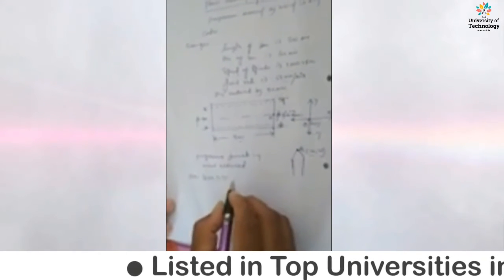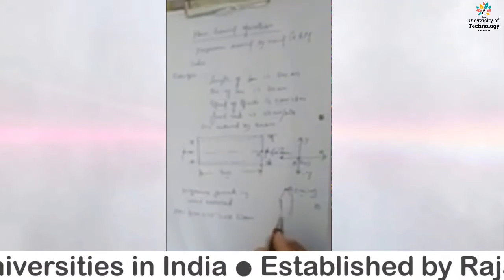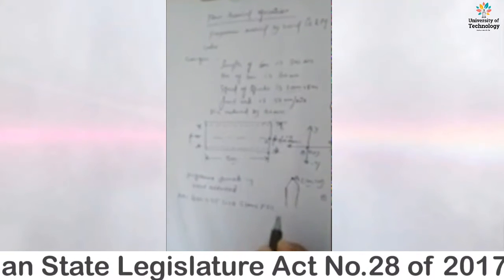G95, and to go to reference we can use here G28, and the spindle speed here is 1000 rpm, and the spindle we represent by capital S, put here, and if we have the fixed feed rate, then we can put here capital F. And the coordinate system in absolute mode, put G90.